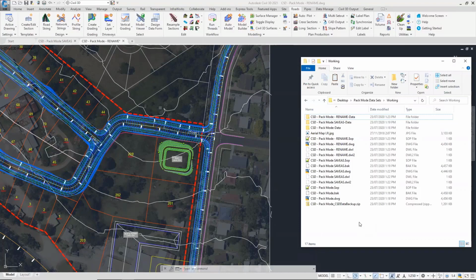Now, let's have just a couple of points here. First of all, auto saving. If your drawing auto saves, that has no influence on any of these settings. That's right, isn't it, Andrew? That's right. And if your project's getting quite large, and we'll talk about that later on as well, you probably don't want it packing every 10 minutes or so.